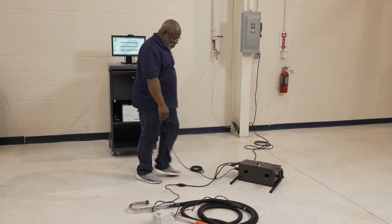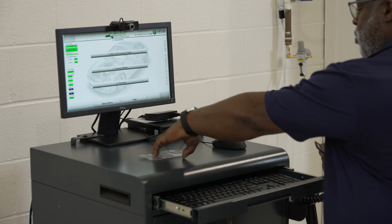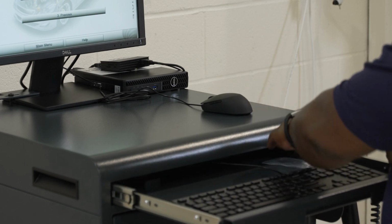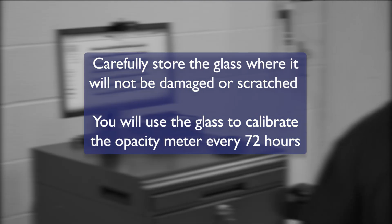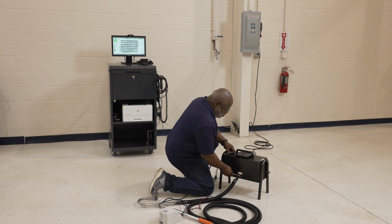Remove the reference glass from the bottom of the opacity meter. Place the reference glass back into its protective sleeve and carefully store the glass where it will not be damaged or scratched. You will need the glass to calibrate the opacity meter every 72 hours. Return the meter to the upright position. Reconnect the heated exhaust sample hose.